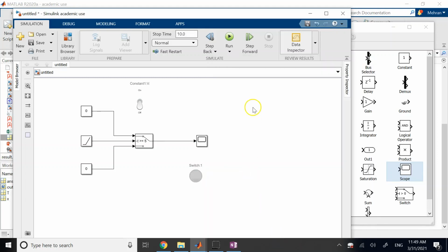So here, now I do the opposite. Look, right? Nothing. And now if I turn this guy on and do it, there we go. And you see, it wasn't on all the way. It was on from after 5 seconds. If I want, I can go here. And now you clearly see the switch is on, but it doesn't turn on because I don't want anything to happen until 5 seconds. So you see, I'm stepping forward, nothing happens until I get to the 5 seconds. When I get to the 5 seconds, then yes, I can turn it on.